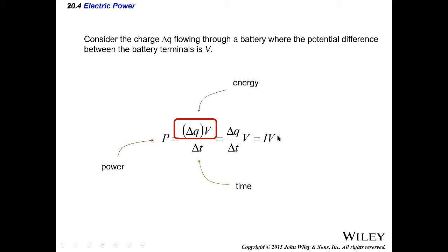Because this now says, you want to know how much power is consumed or supplied by this battery. If you want to know how much power is supplied by this battery, you measure the current that flows when you connect it and the voltage of your battery, V. Then the power is I times V. If you use I in terms of amps and V in terms of volts, then automatically I times V is the amount of power, so many watts.